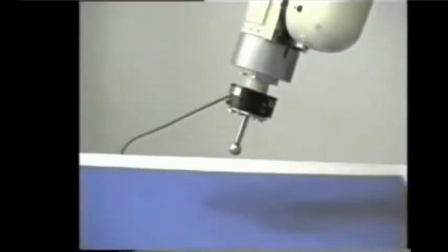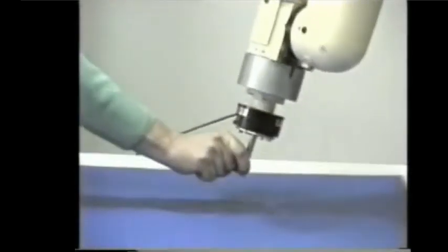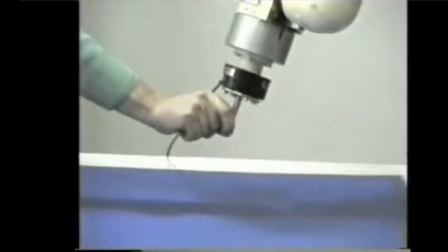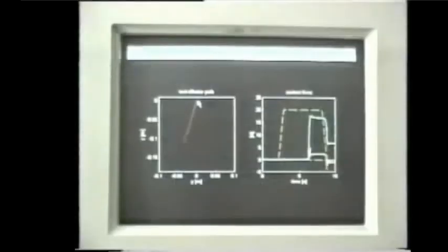Instead, if the inner loop is a velocity loop, you can see it also from the approach phases that the end effector is drifting from the vertical. Even at the contact, there's a mistake by this type of loop, which is not recovered. So you're going down in the free space along a diagonal path, which is not the right one. And again, when you're in contact, you're not realizing the desired force. There's a residual steady state force at the contact. And there's an extra normal tangential force, which should not be there.